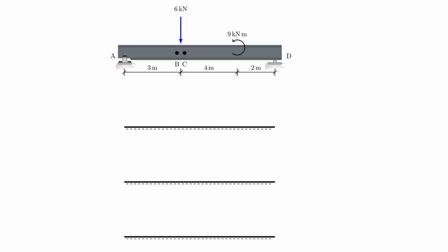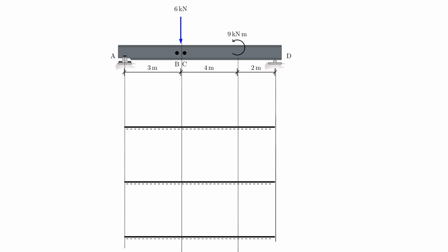But let's go ahead and first bring down our lines here. That always helps me to line up my diagrams better. And then also the next easiest thing to do is probably to draw the indicators for the individual lines, for the individual diagrams, I should say. So of course I start with my normal force. So let's put the normal force right here. And in this case, we're dealing with kilonewton. So I have to put that unit here as well.